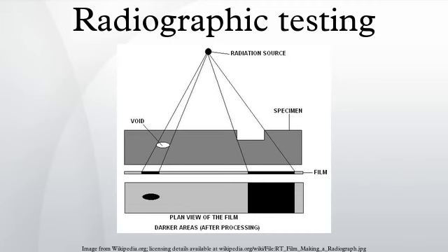To the trained radiographer, subtle variations in visible film density provide the ability to not only accurately locate a defect, but identify its type, size and location. An interpretation that can be physically reviewed and confirmed by others, possibly eliminating the need for expensive and unnecessary repairs.